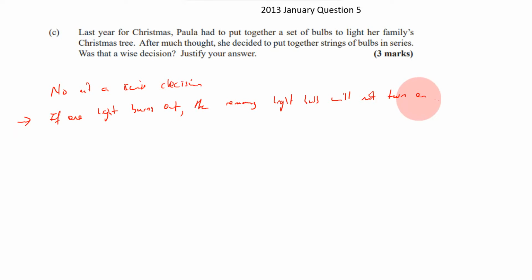And we know with Christmas bulbs, it's quite obvious that they will blow over time. So if you connect all of those bulbs in series, and one of them blows or goes bad, then the whole entire thing is not going to work. So you wouldn't want to do that. So that's one of the reasons.